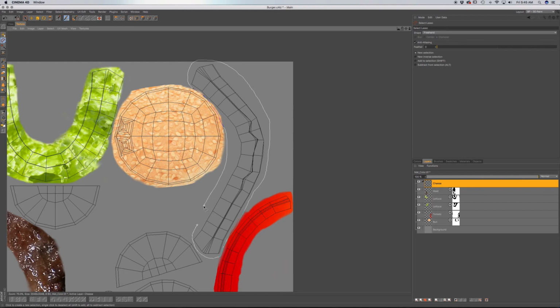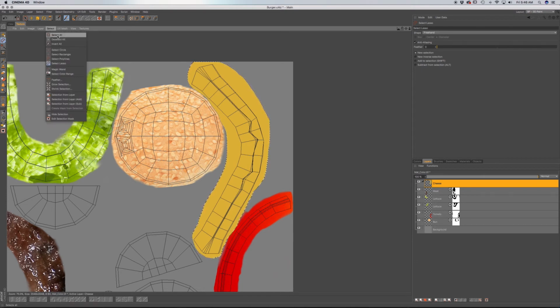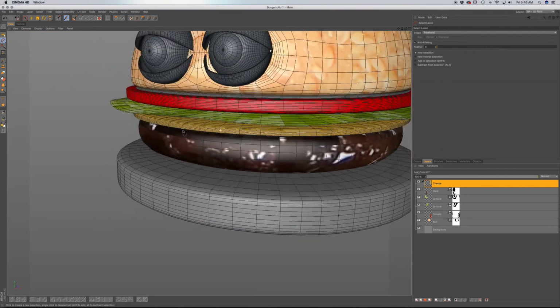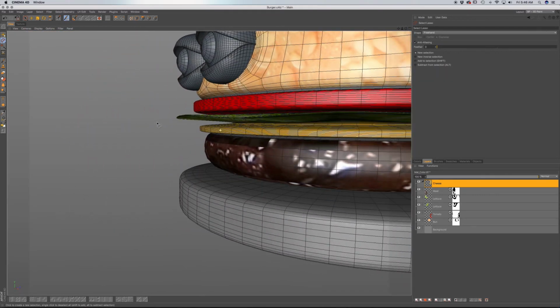And it's okay if you're on top of the other image because we have a new layer. What you can then do with this foreground selected, you can go to this icon here, click and hold, and go to this paint bucket fill, and that's going to fill that area. So I'm going to deselect all, and then 3D view. You can see now we have that color in this area. Okay.